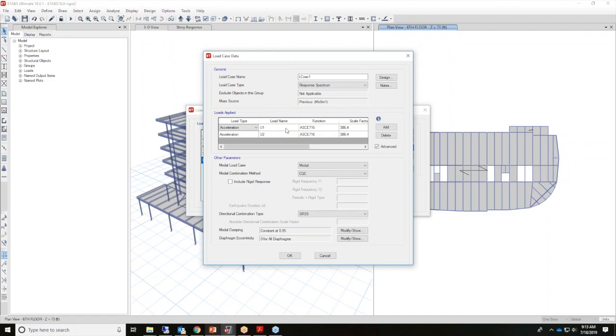To perform this correctly, it assumes you know the critical direction of the earthquake motion, as well as the principal axes of the building. So in ETABS, by using the function in both orthogonal directions and using the SRSS, or square root sum of the squares method, for directional combination, the maximum may be captured using a single analysis run.